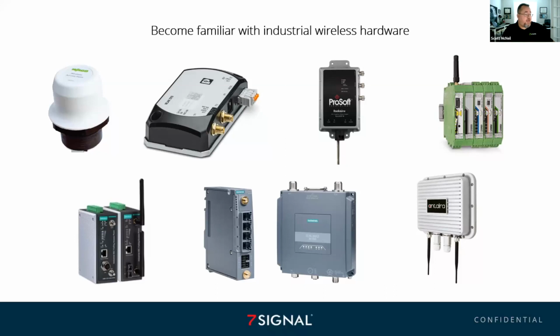Then you have something like this, which is a wireless IO radio, input output, specifically designed for industrial communications. So you don't log into this to configure it. There is no web interface. It's all configured on the dial on the front. It uses a proprietary protocol, although it is based on frequency hopping. And this just communicates to other nodes similar to it, and then talks directly to your PLC or DCS. So this guy is a completely different animal, and he's running at 900 megahertz.